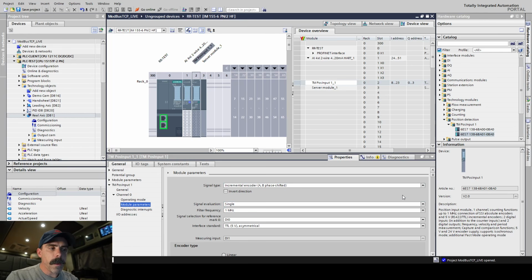So you have either A, B tracks that are phase shifted, because these are going to be 4 wires, and there's going to be A and B, just like we talked about before. A, B, they're phase shifted. You can have redundant tracks, an A, B, and a neutral, or a 0 pulse, so it knows when it hits the 0 pulse.